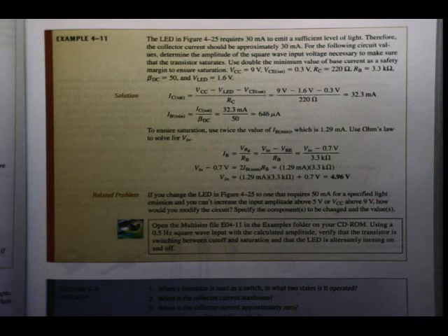Remember, we've said earlier, I'm limited by my circuit for the maximum current. So at some point, I can increase IB as much as I want, but IC cannot increase because of the limitations of my circuit, as we've seen. IC sat is equal to VCC, a set voltage, minus the saturation voltage of VCE, 0.2 volts, divided by the resistance, whatever the circuit may be up to this stage, RC.